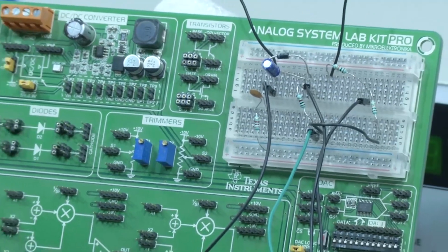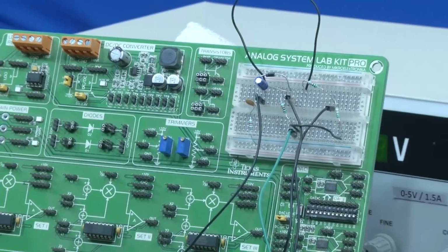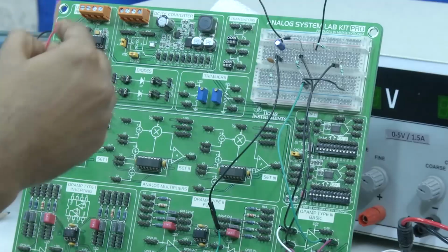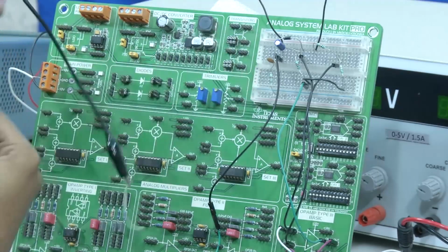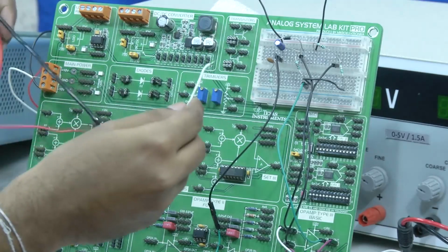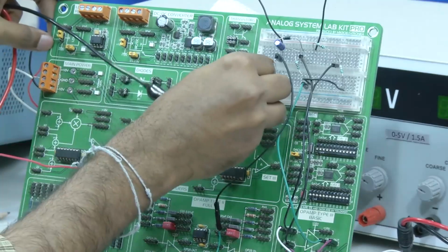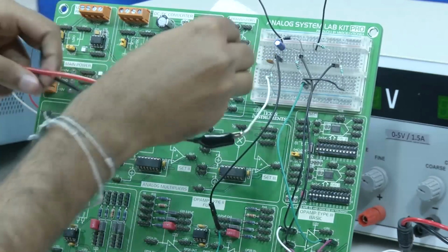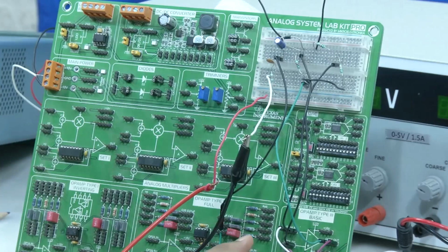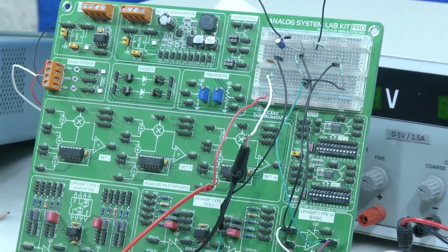So, what we do is that the input from function generator, the negative should be connected because we require a negative spike. The negative should be connected to the capacitor and the positive should be grounded. Now if you observe, the ground is connected to the other part of the resistor, and the white color wire, which is the ground of our function generator, is connected to the capacitor input. Now, we will observe what is the response we get.